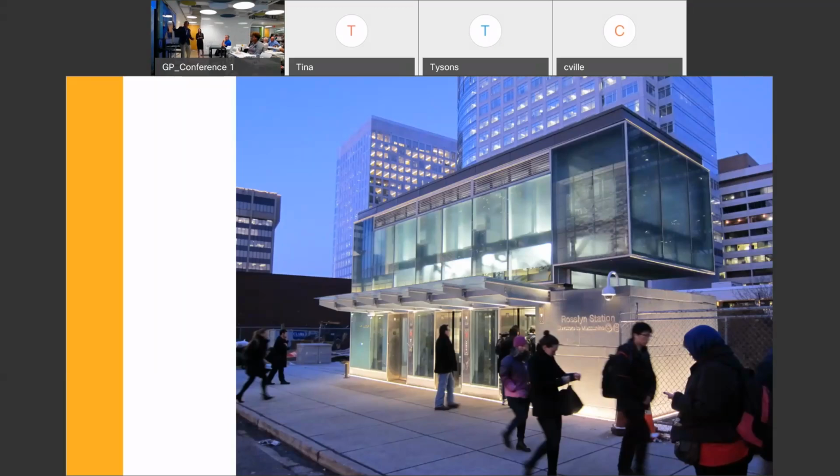And the challenge was to get this floating cube. If your glass is not textured enough or frosted enough, it's not going to absorb the light either. So you're not going to get that contrast of that floating element that you're trying to achieve. Same thing if you put downlights here, then you're brighter down here, and the contrast is going to be different, not giving you that architectural element that you're trying to achieve.